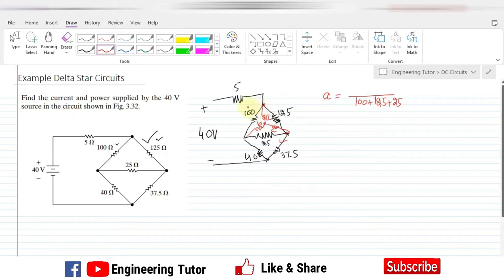There are only two resistors connected with this junction, 100 and 125, so we multiply them together. That becomes 12,500 divided by 250, the sum. So we get 50 ohm here.